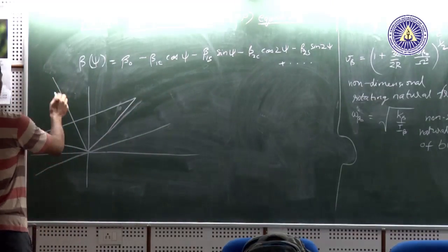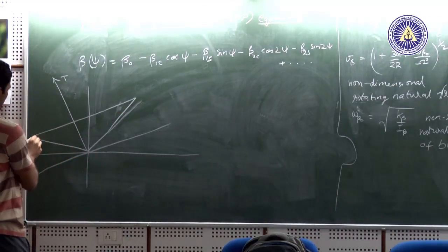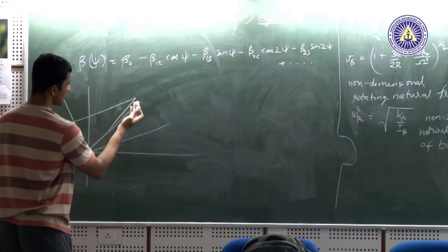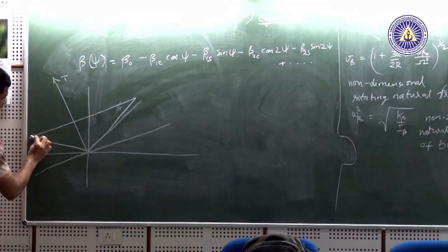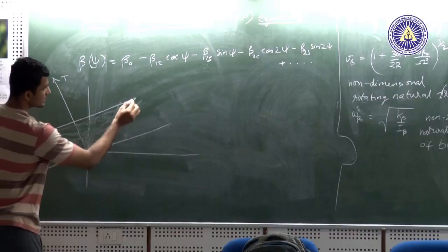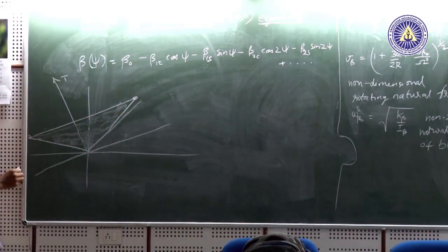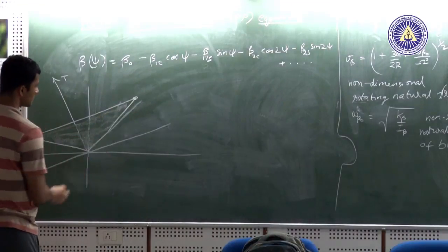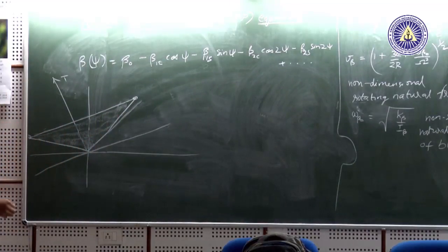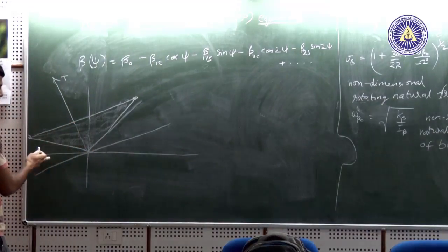Okay. So this is my thrust vector. So this is how my rotor disc is going to, so this is the tip of the rotor and this is like the blade, and when the blade rotates like this, you have this conical region, and this is the tip of the blade and it will be traversing like this. So this makes a cone, and this plane is known as the tip path plane. Okay. And we can describe the orientation of this cone with respect to the hub plane.